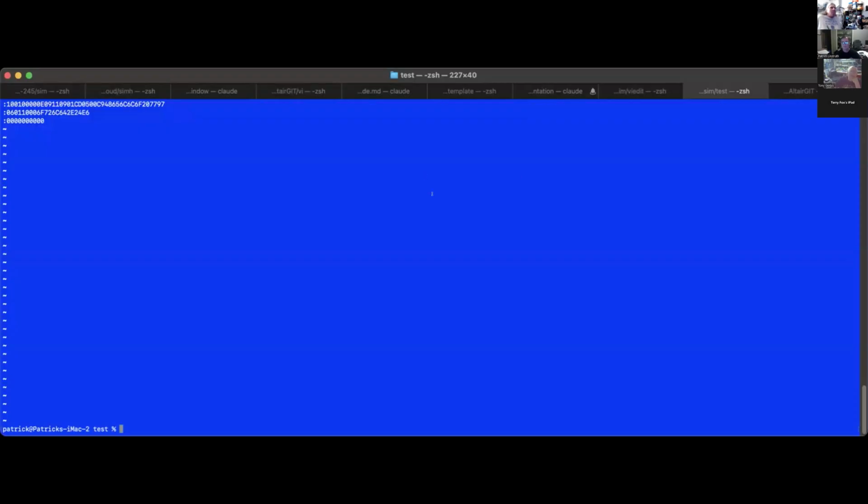That must be Intel Hex right there. Yeah, I see it. It's Intel Hex, because it starts with a colon and a one, and the addressing is actually starting at 0000 for what you're burning into the PROM. So that's the first address of the EEPROM itself, and that should be 16 bytes or 32 characters with a checksum of 97. This is the ROM. I made a ROM a while ago. I got Altmon in here, kill the bit, SIO loopback tests, JWD bootloader. But I just use the hex files and load them up with the program that came with it that only runs on Windows.